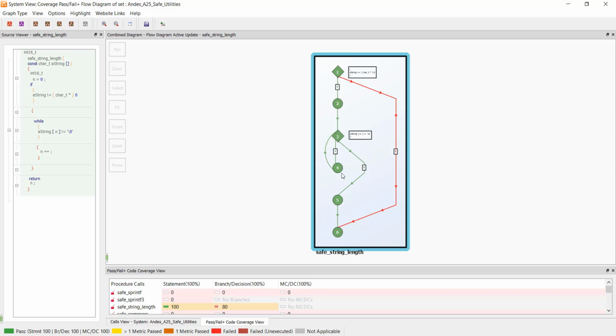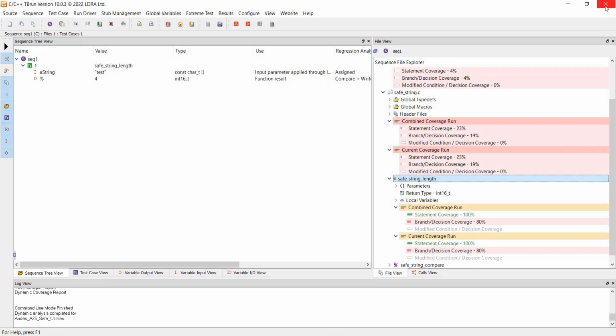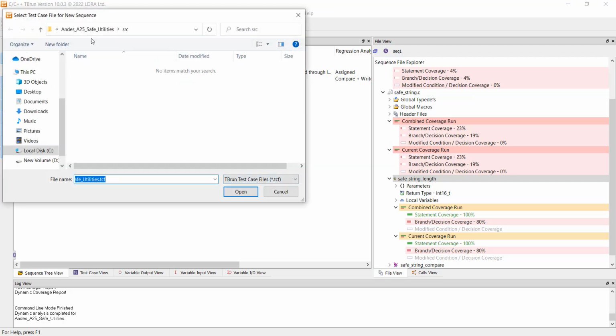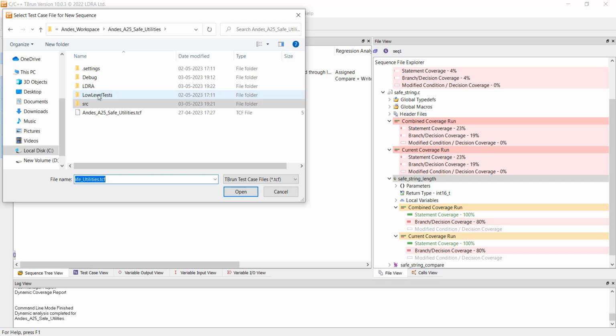We can see all the sections of the code have been covered, whereas this particular branch, the false statement, has not been executed. So we can create multiple test cases, and then we can pass appropriate conditions for it, such that we can hit 100% coverage. So we need to provide appropriate data for each test case to hit the appropriate conditions to get the 100% coverage. I have a few test cases with me. I'm going to import those test cases.